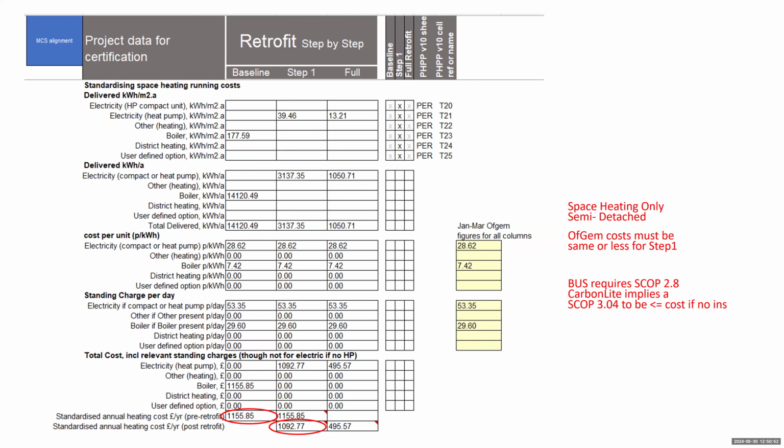We've had another question come in from Andrew Allen. Thanks, Andrew. A question I've come across many times is, how do you prepare a retrofit so that you don't sabotage a future upgrade? For example, if you want to improve your windows and undertake EWI but can't afford to do both, one can either decide to do a poor installation, such as upgrading the windows and then adding EWI afterwards, which means the windows won't be in the insulation zone. Alternatively, one would have to resort to disrupting either the EWI later or the windows. What would you do in this scenario?